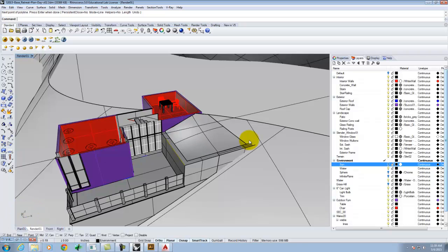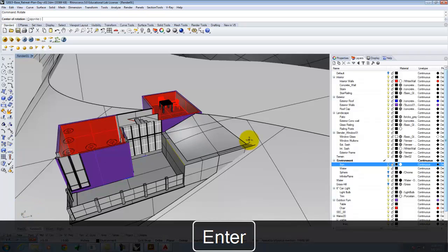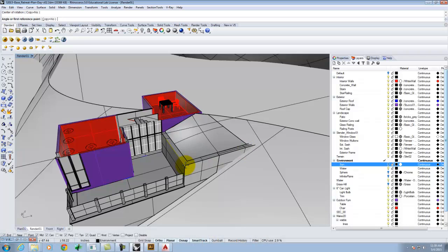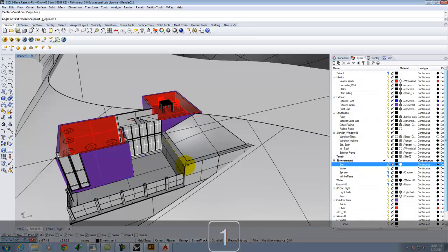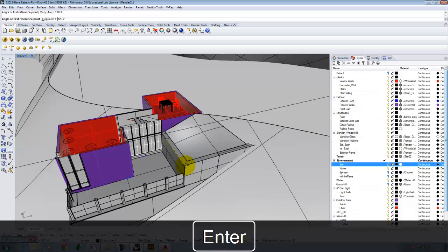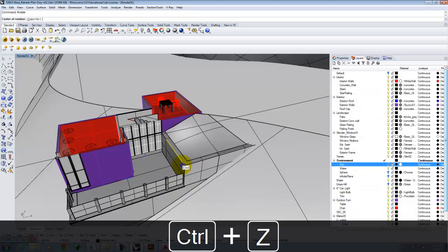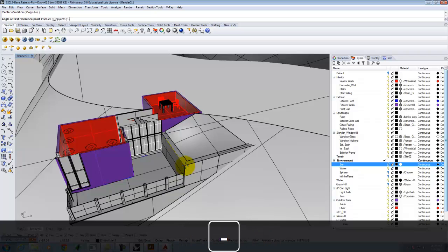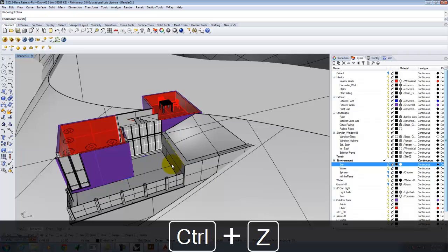And so then I'll start by typing rotate. This isn't 3D rotate. It's just a basic rotate. And the first rotation is going to be this first number, 128.2, actually negative 128.2, sorry, because we're rotating to the south. There it is. Right, now I need to rotate 3D. Oh, I should have done that first because it's on axis.